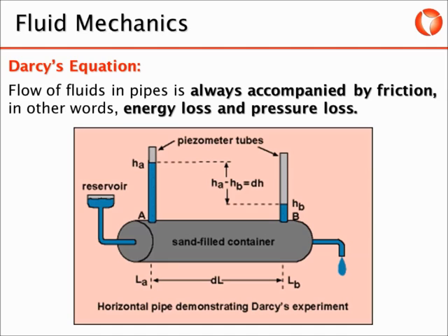If two manometers are connected to two different sections of a pipe with a running fluid, the manometer at the inlet section of the pipe will indicate a greater static pressure than the one located at the outlet section, due to the pressure loss. It is necessary to quantify this energy loss to be able to adequately design the piping system.